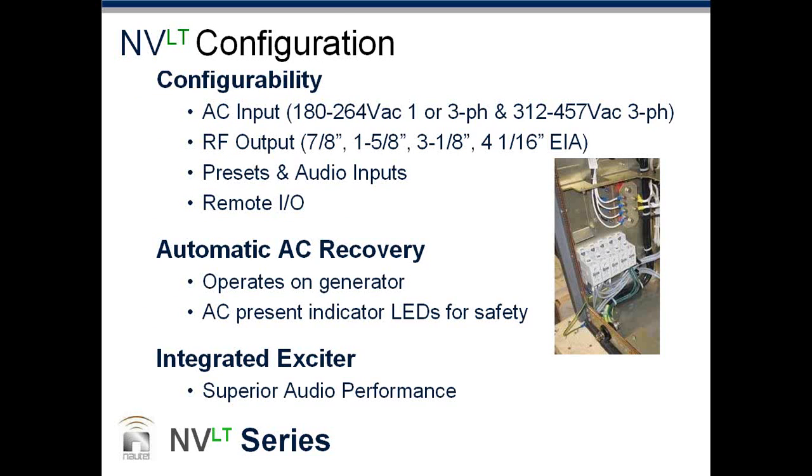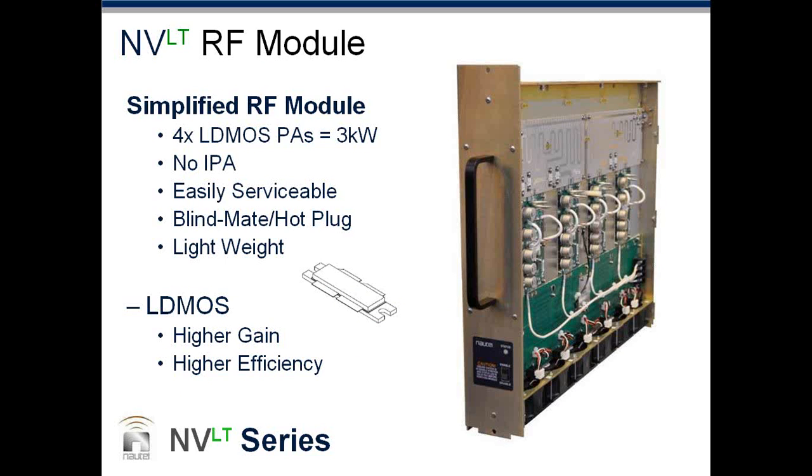Can we just go back for a second? Sure. So it operates on generators. One of the things there, the power factor of this transmitter is near unity. So generators like that. And secondly, we do have software that does allow for a soft start under generator operation. So if you don't like the big step function from 0 to full power, we can gradually turn on the transmitter over several seconds or even minutes. That's great.